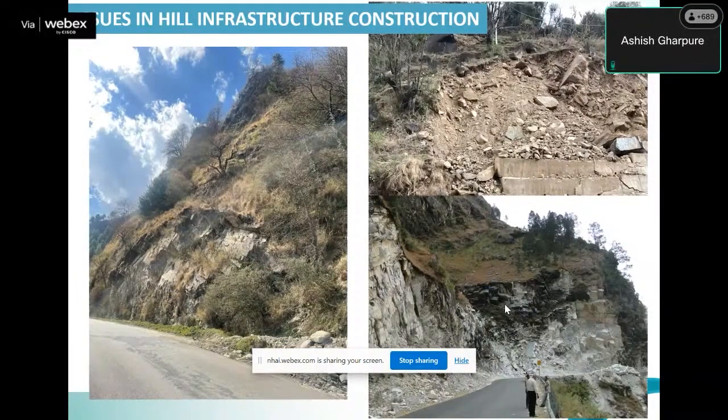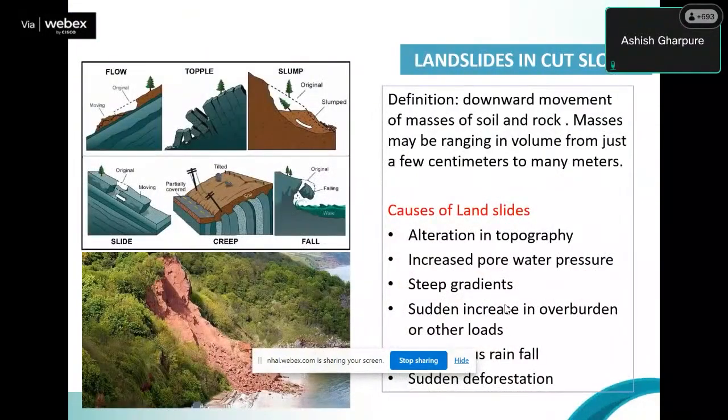Then we also deal with rock cut slopes. Now, some rocks can be very stable, and you can cut vertical and it will be stable. However, we need to monitor each rock type and its bedding planes, joints, and detail to know what kind of failure is possible. So there are favorable and unfavorable conditions of rock cut slopes. So we'll deal with it as we go next. And there are conglomerate material as right top corner screen you can see.